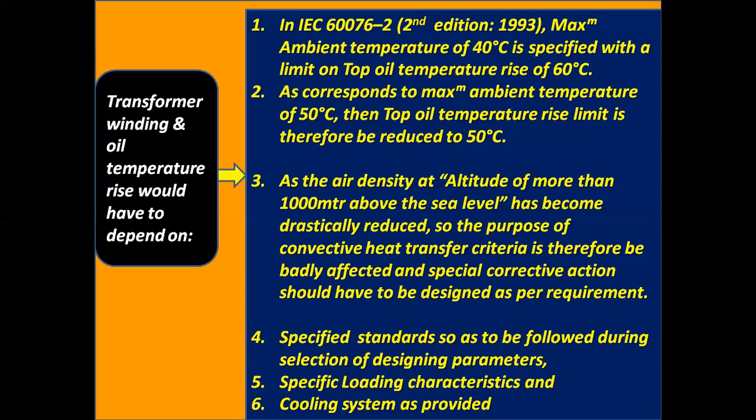Number three is the most important one. As the air density at altitude of more than 1000 meters above the sea level has become drastically reduced, the convective heat transfer criteria is therefore badly affected, and special corrective action should have to be designed as per requirement.